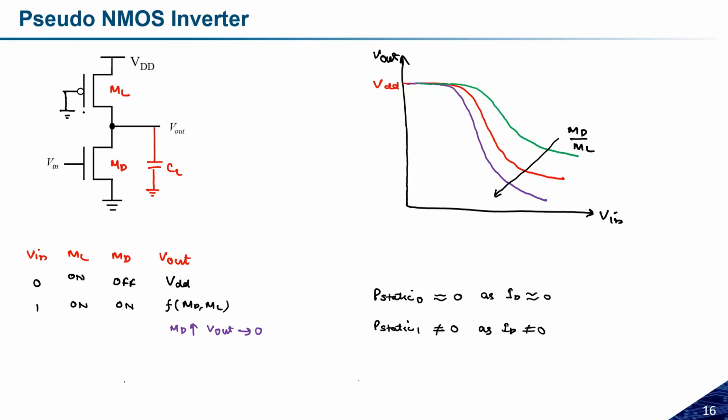So in one respect we are getting a benefit, we are getting the better noise margin. Yes, of course, the power dissipation will be approximately the same in both cases. But if you are talking about the area requirement, the area requirement in pseudo NMOS will be larger than in the enhancement load inverter. Did you get the answer? Did you get the point of what I'm saying? Can anyone acknowledge? Okay, so this is the important thing.